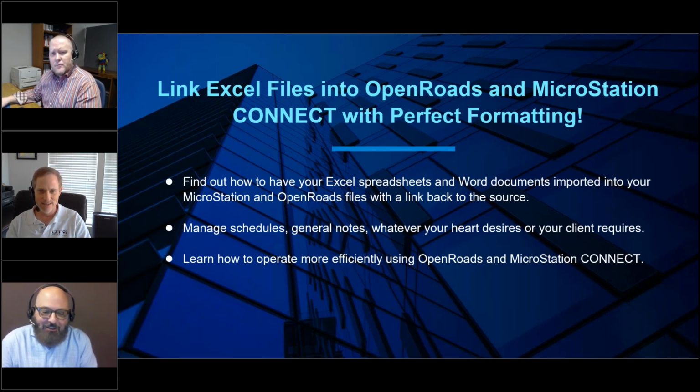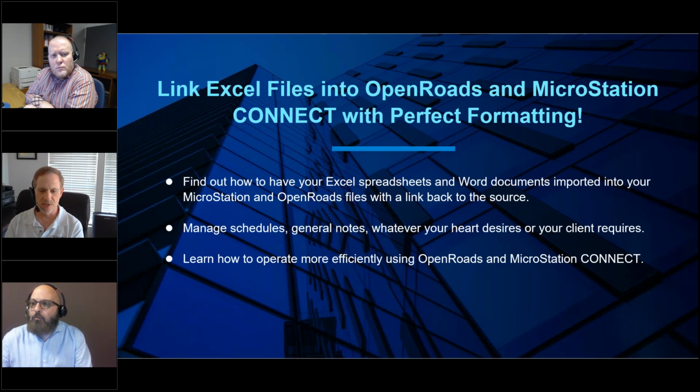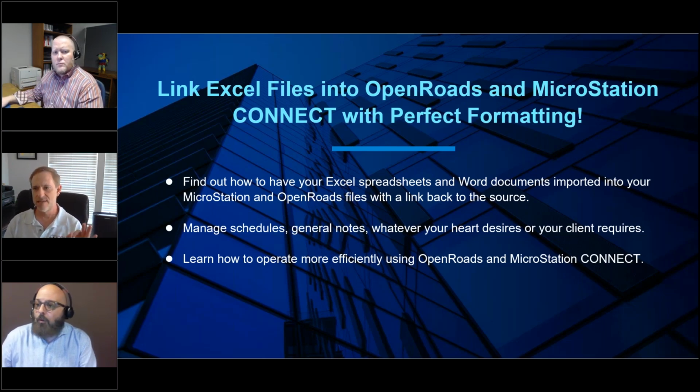Great. That's exciting. So Dan, would you cover just a little bit about what we may be covering in today's plugin review webinar? Absolutely. We use OpenRoads Designer Connect Edition, and it's a great program for corridor type designs. So in this demo, I think we've got 26 miles of roadway. We're just going to quickly have a horizontal alignment, a vertical alignment, and then design a quick corridor on it, and immediately go to reports and generate those reports, then use Axiom's Office Importer and bring those back into MicroStation. Check the format, make sure everything's correct, and we'll show that quite a few times in the upcoming videos.